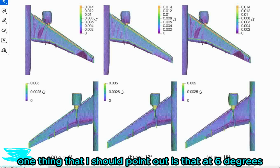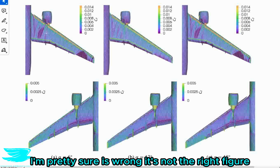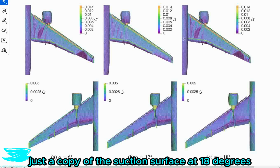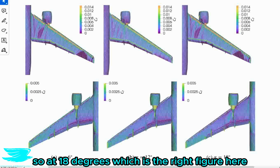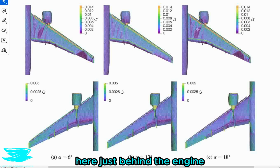One thing that I should point out is that at 6 degrees, the suction side, I'm pretty sure is wrong. It's not the right figure. It's actually accidentally just a copy of the suction surface at 18 degrees. So let's ignore that figure there, but let's look at the rest of the figures. So at 18 degrees, which is the right figure here, there is one very large region of low skin friction here, just behind the engine.